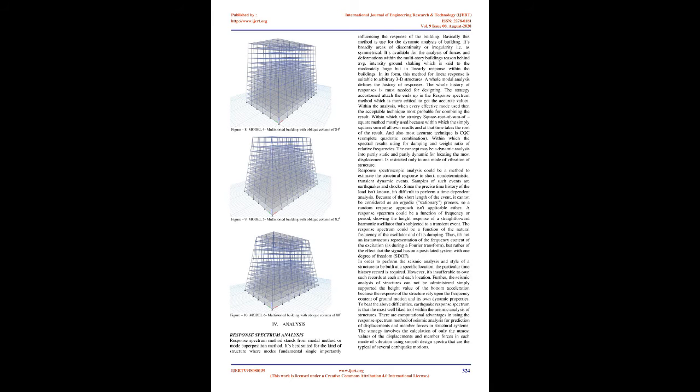1. Utility of buildings, multipurpose. 2. Number of stories, G+12. 3. Shape of the buildings, rectangular. 4. Number of staircases, 2. 5. Number of lifts, 1. 6. Types of walls, none. 7. Geometric details. Ground floor height, 3.6 m. Floor to floor height, 3.6 m. Height of plinth, 0.6 m above G.L. Depth of foundation, 3 m below G.L.